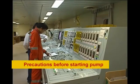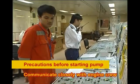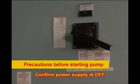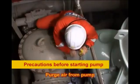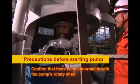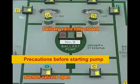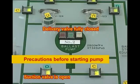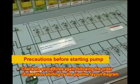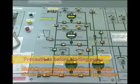Before starting the ballast pump, attend to the following. Communicate closely with the engine crew to avoid any accident due to lack of communication. Confirm that the power supply is switched off. Purge air. Confirm that there is no abnormality with the pump's rotary shaft. Confirm that the suction valve is open and the delivery valve is fully closed. Just before starting the pump, check the procedures again, following the order of operation, abiding by the pipeline layout diagram.